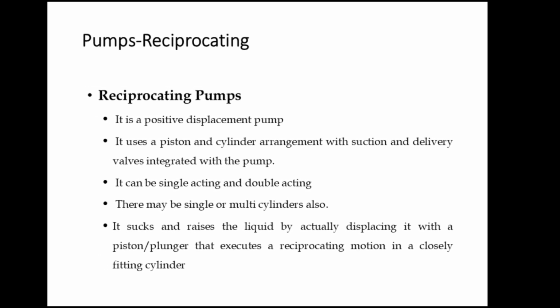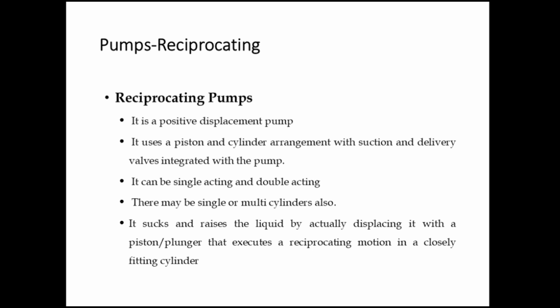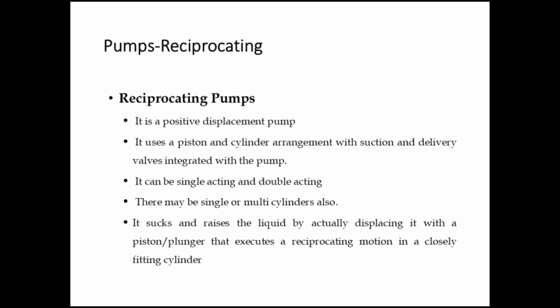Reciprocating pumps. It is a positive displacement pump. It uses a piston and cylinder arrangement with suction and delivery valves integrated with the pump. It can be single acting or double acting. There may be single or multiple cylinders also. It sucks and raises the liquid by actually displacing it with a piston plunger that executes a reciprocating motion in a closely fitting cylinder.